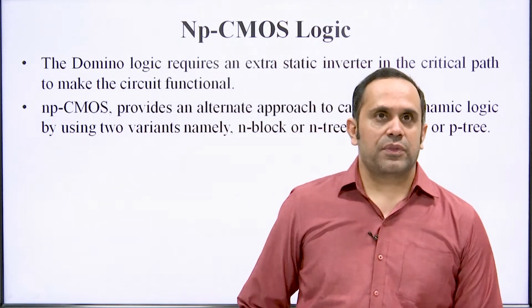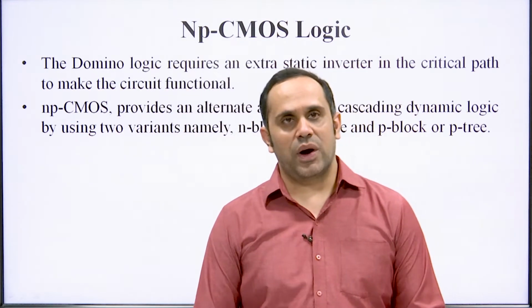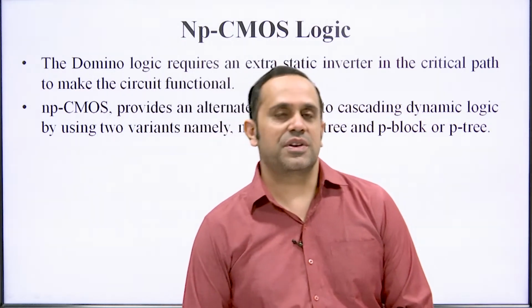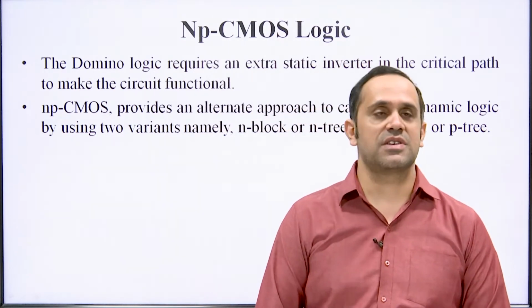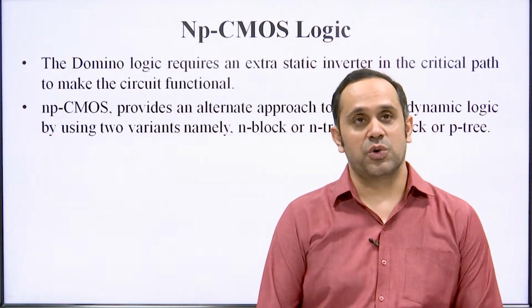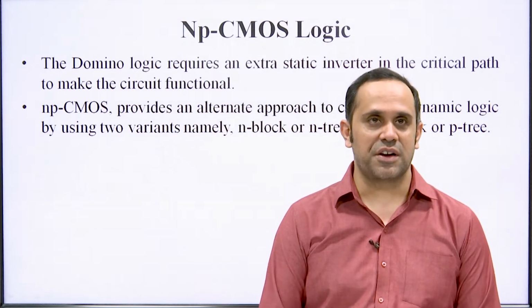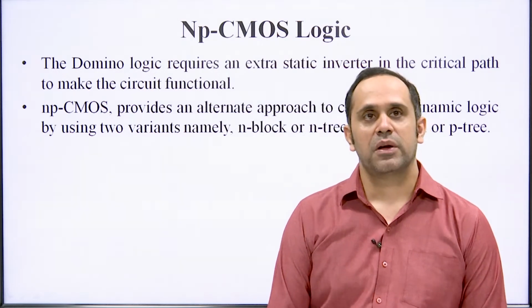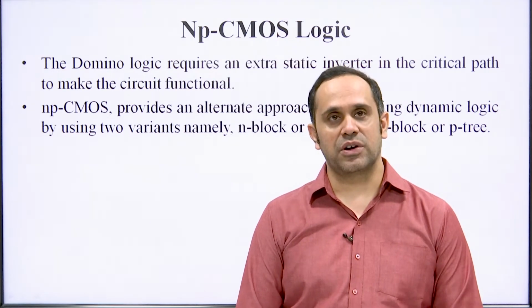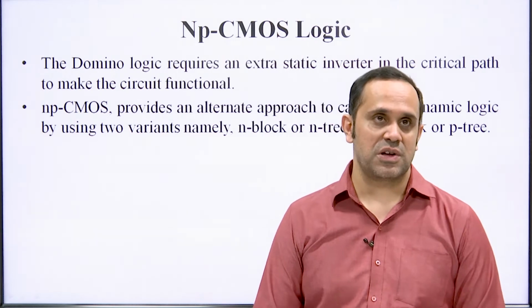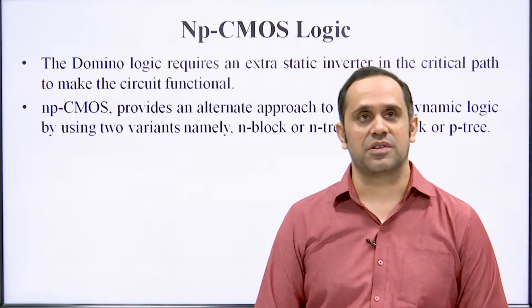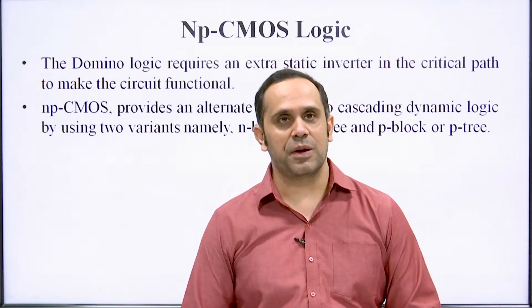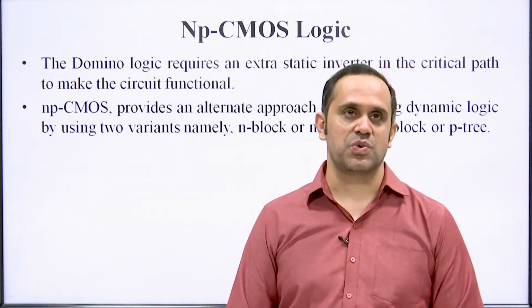So, till now we have seen quite a few design methodologies. We have seen static CMOS design, where there is no role of a clock, the signal remains as long as they are there, the output keeps on calculating. It offers very good noise immunity, it is very robust, but then it uses a lot of transistors. So, scalability, increasing complexity is an issue.